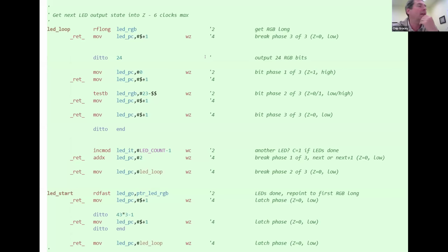And on the back side, I don't have a picture of the back of the board, but there are these little spark gaps built into the circuit board where you have exposed little tiny fingers that come within like 6 mils of each other to concentrate any electrical field if there's a big voltage buildup. So it begins an arc, which then drags things. The arc will probably burn until you're down to like 20 volts or something, and then it will go out. So it takes some of the burden of protecting the board off of all those other components, like the transient voltage suppressors and the fuses to a lesser degree.